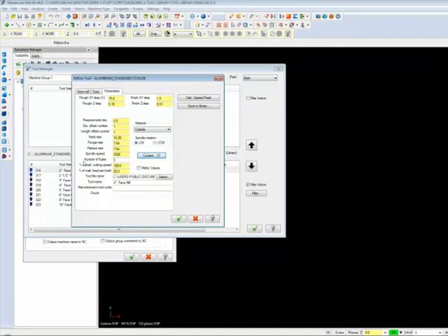Let's rename the tool to reflect that it's in our aluminum library. Enter the manufacturer's tool code, which is Ingersoll 5H6G-20R01, followed by the inserts we're using, SHET 110516FR-P.